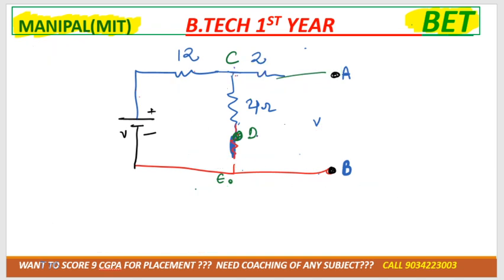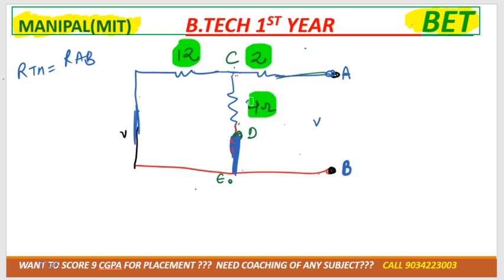So voltage source must be short circuit. So all the voltage sources, it is not that you remove only one voltage source. You need to short circuit the voltage sources. Now you need to calculate RTH, that is equal to RAB. Again, where are you standing? At A. Where do you have to go? To B. Just imagine 12 ohm, 2 ohm and 4 ohm. These are your friends. Okay? So you will start with the friend who is very far away from you, that is 12 ohm.